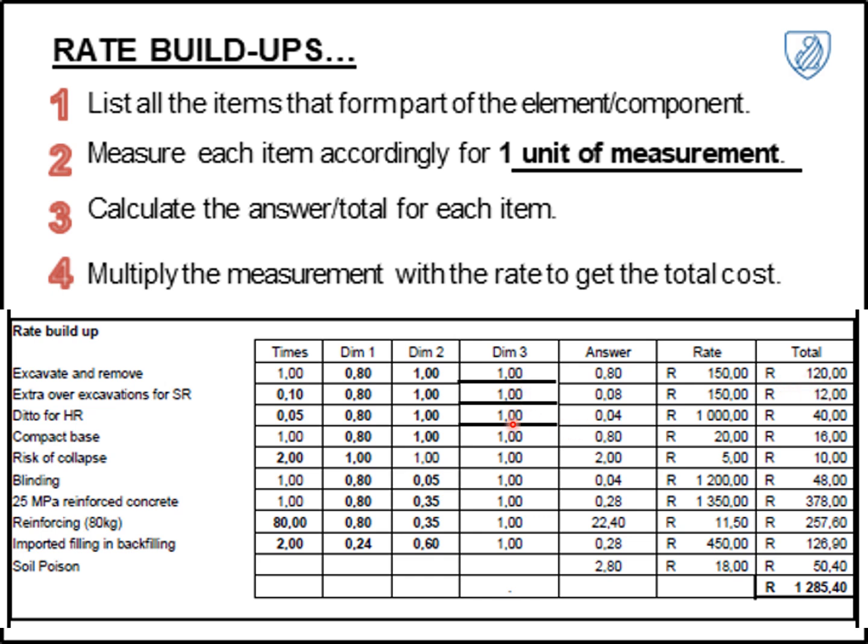The 1 here is converting it to a 1 meter section. So for an 800 millimeter wide and 1 meter deep excavation, for 1 meter in length, we times that together to get our factor that is applied to our rate to get to the rate per meter.